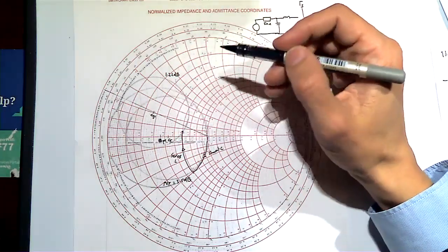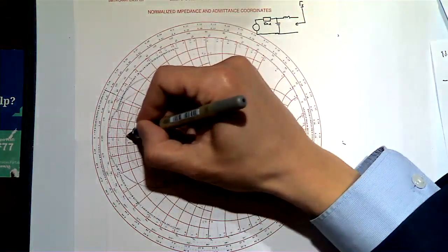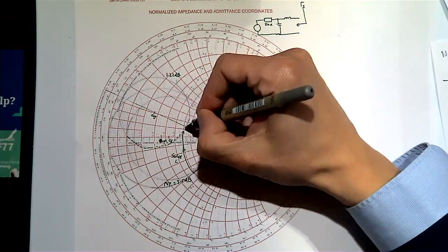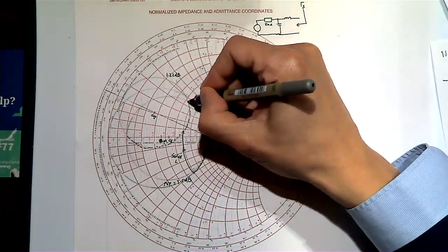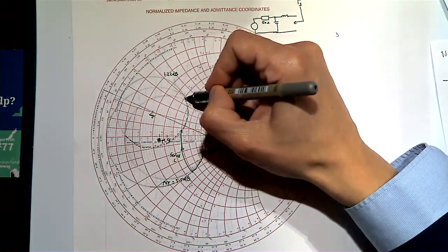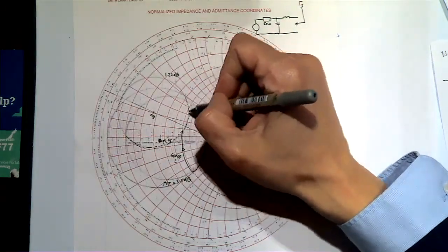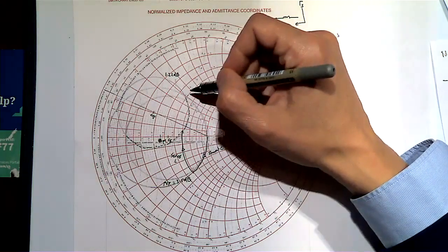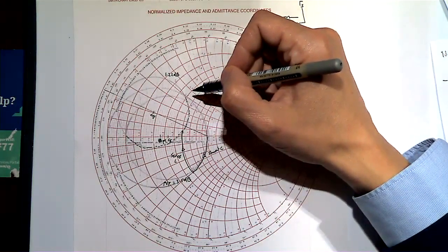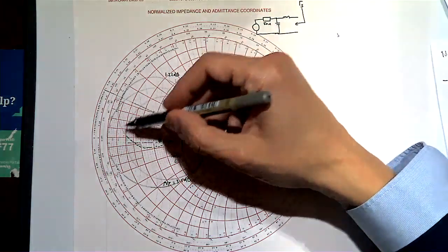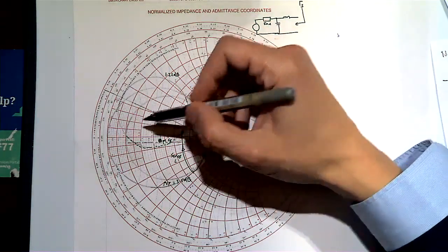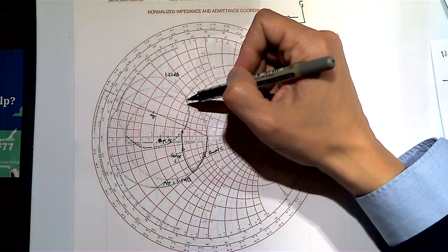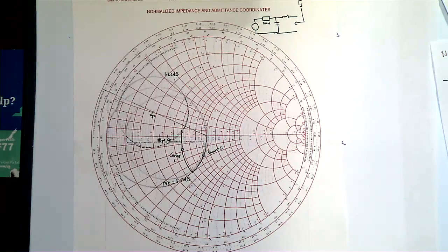So essentially, for everyone's benefit, anywhere here, if I wanted a gain of 1.22 dB and a noise figure of less than 3.5 dB, anything on that arc will give me those characteristics, because it's inside the 3.5 dB noise figure circle and it's on the 1.22 dB gain circle. Right, now, any of those points are valid.